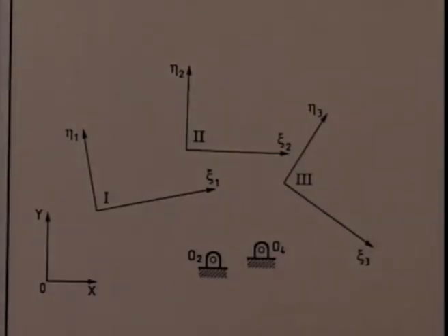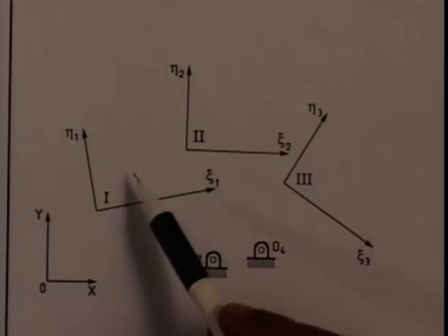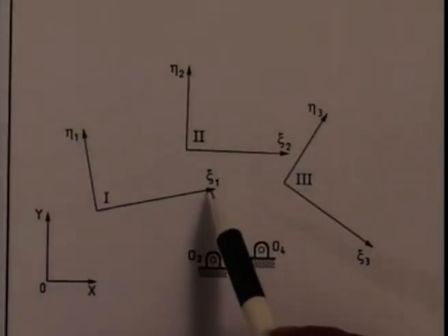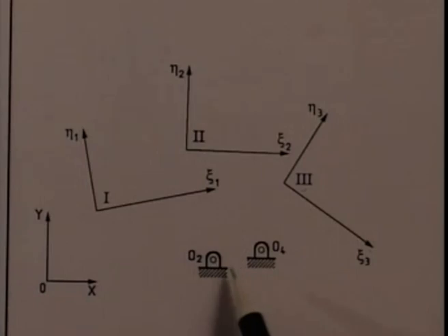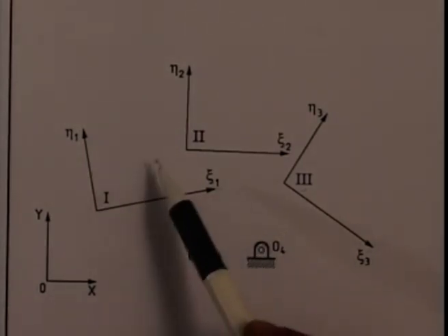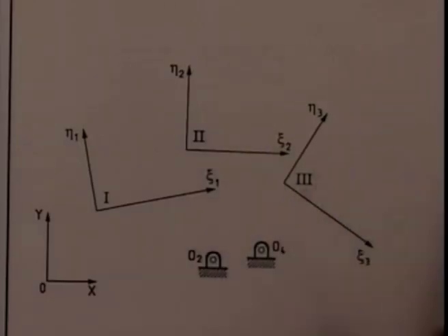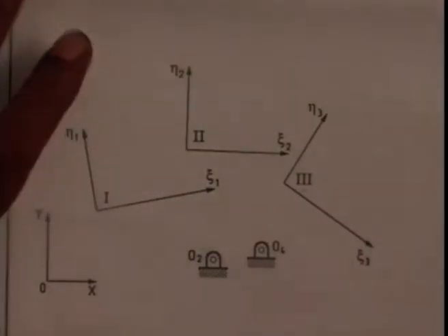To solve this problem, as I said earlier, we shall use the principle of kinematic inversion. To locate A1, B1, what we do, we fix the coupler at this first position and let O2, O4 move, keeping the same relative movement as prescribed here. So let me do this inversion by using a tracing paper.